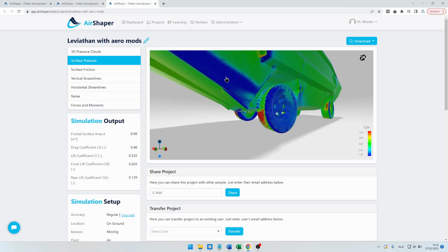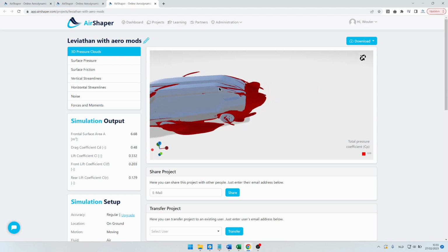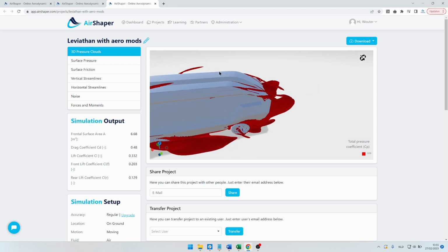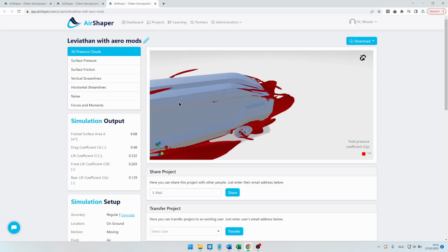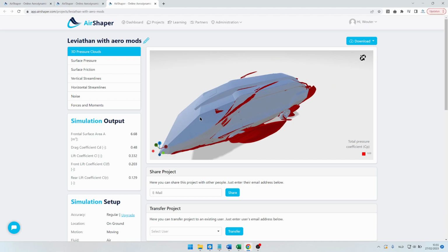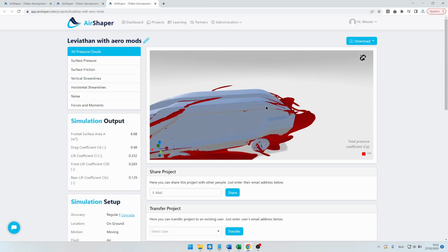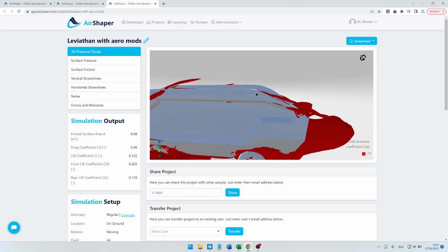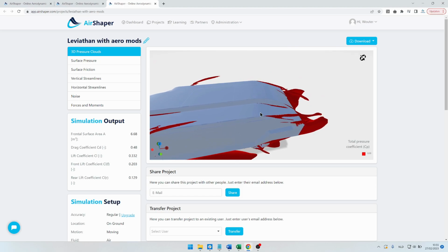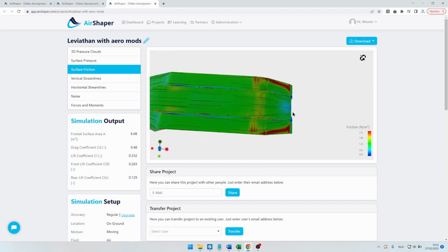And then if we move to the back of the Leviathan, we can see that they added this nice round here because this was a different construction method compared to the front. This was more difficult to modify. This one could be modified. I think it was made up more out of composite materials, so more freedom in terms of molding and so on. So this round shape now makes it possible for the flow to stay attached, which you can see by the surface friction to some extent. You now have nicely parallel streamlines here.